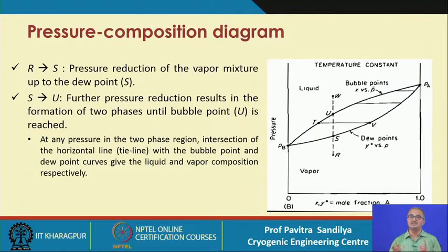Only thing is this, the names are different because compressed liquid means that we are getting the liquid by compressing a vapor, whereas subcooled liquid means we are getting the liquid by cooling a vapor. So, these two processes are different to obtain the liquid, even though the state is one and the same. So, subcooled liquid and compressed liquid mean the same thing.